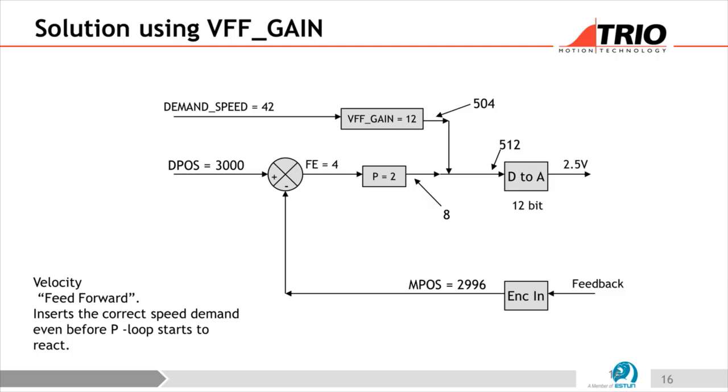So most systems use that, and I don't really get involved in helping people set up PID loops, because it's a nightmare. Do we have any auto-tuning functions either in this or in the drive? Well, the drive will have auto-tuning functions probably, depending on the drive. We don't have any auto-tuning for the P loop. It's not a trivial thing to do, should we say. It's quite complex, because you have to take account of inertias and all sorts of things. And I have no idea what the maths is for auto-tuning a P loop.